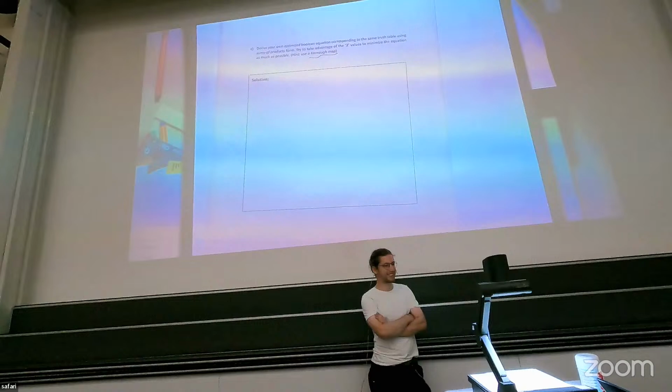It matters if you are in Safari group and you're trying to do RowHammer, because which memory address is physically next to which memory would change according to how you assign these bits. Because data will be written either 1, 2, 3, 4, 5, 6, 257, 258, 259, or it would be written 0, 1, 2, 3, 4, 5, 6, 7, 8, or any other weird combination depending on which bit you pick.